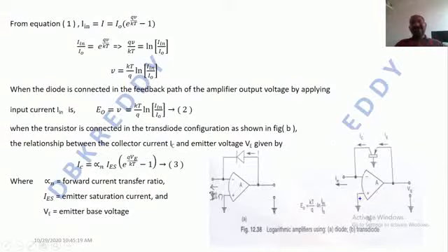If you see this one, as all of us know, how much voltage is there at the non-inverting terminal input? The same voltage is there at the inverting terminal. Means it is a virtual ground property. We are having one property called virtual ground in operational amplifier. I'm not here to elaborate the explanation related to the virtual ground. So the virtual ground statement says that how much voltage is there at the non-inverting terminal, the same voltage will appear at the inverting terminal of the op amp.